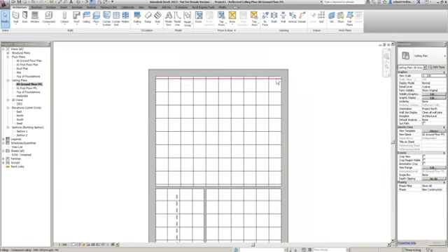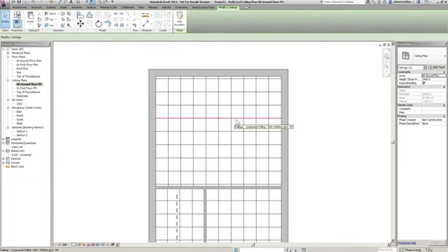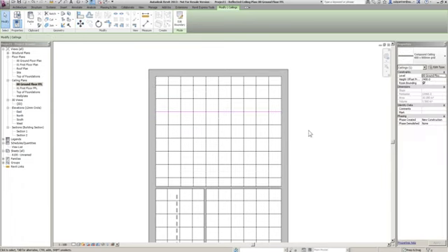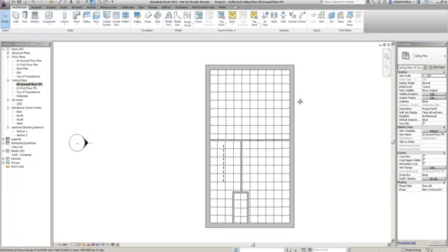For example, in reality, I'm going to move this grid. Now what I'm going to do, I always teach people to create things on their BIM model how you're going to do it in the real world. So in the real world, if you've got a silly little cut across there, your entire grid system would move half a tile. So that's exactly what we do. But we don't move half a tile, we pick one of the lines involved in the tile, move from here, go up 300, which is half a tile, done. And the rest of the grid will just basically align to it.